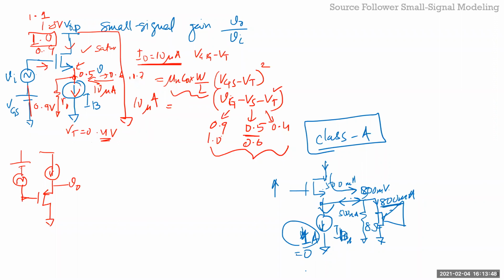But for really small amplifiers where you have small currents, you just bias it class A, because if you try to do class AB for very small, then you end up actually burning more current, your circuit being more complex, your circuit being more area, and so on. So typically when we are doing 100 microamps, 10 microamps type of amplifiers, they're just class A's, even half a milliamp, depending on your application. If you can't tolerate that kind of power loss, then obviously you have to think about other ideas. Okay. So that's what's called the bias current for a class A amplifier.